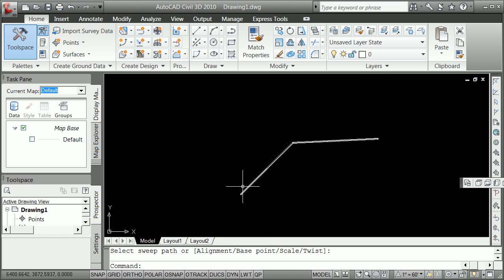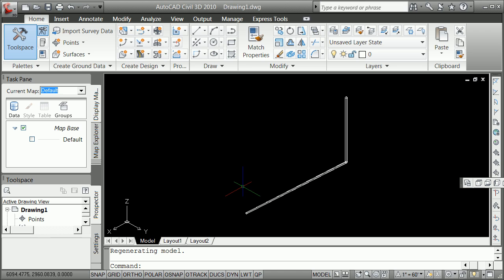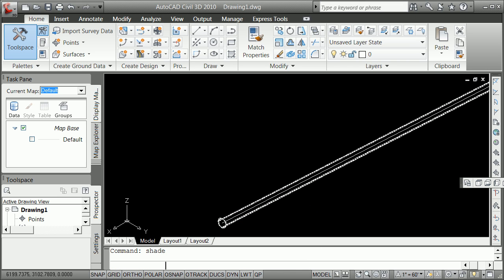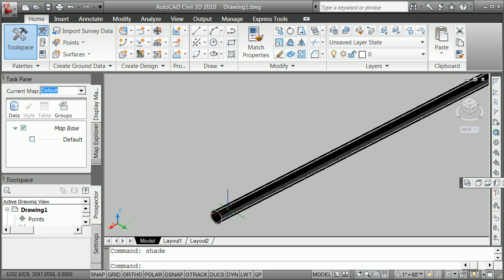So I'm going to see if I can do a V point 1, 1, 1. We can zoom in here, do some shading. We'll have to see exactly what it did here, but it essentially made that pipe and it swept it all the way through. So extrude and sweep, they're a little nuanced, but you could have done the same thing if you would have had separate, and we've got a minute here, so we're going to try it anyway. You would have had separate basically templates or assemblies or just basically blocks that were put at 0, 0 or defined at 0, 0.